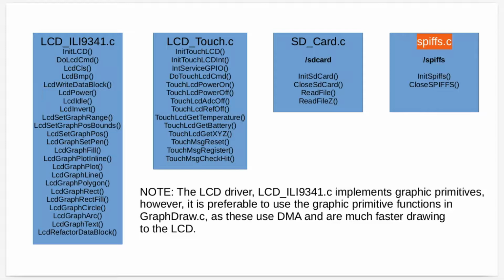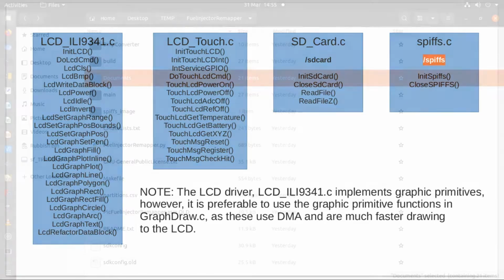So if you didn't want to use the SD card slot, you could just use the flash drive, which is the program flash, and place files on there, which you can get to through this particular directory, which is /spiffs, then / your file or subdirectories and your files.